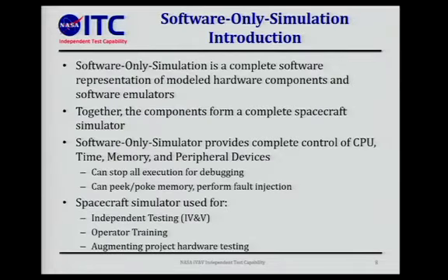So a little bit about software-only simulation. It is a complete software representation of modeled hardware components and software emulators. Together, this forms a full spacecraft simulator. What this means is our team, we usually go to the NASA centers and we find racks of hardware and we virtualize that and we turn that into software-only simulation so that we can execute the flight software on a typical server or a laptop without needing 1553 cards hardware, without needing spacewire hardware, without needing that underlying hardware. We just cut all that out and then we build a software-only simulation.